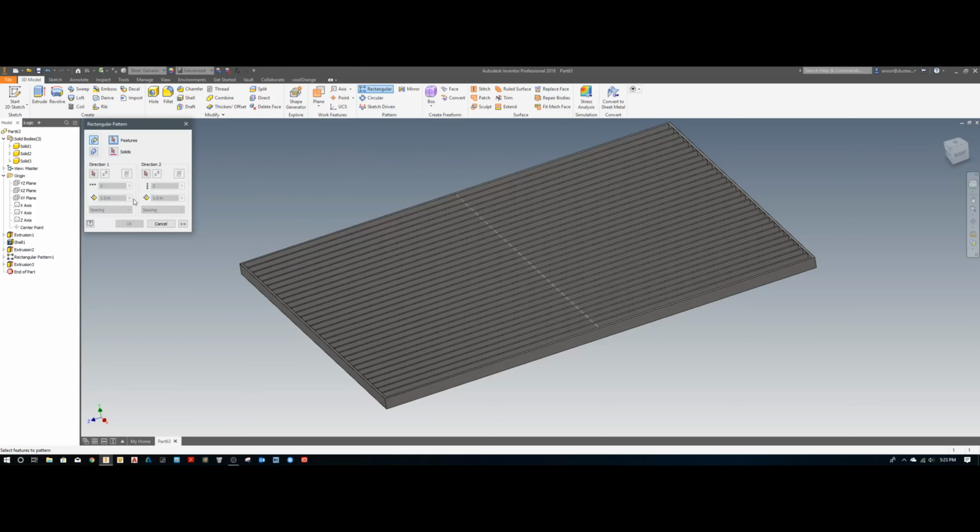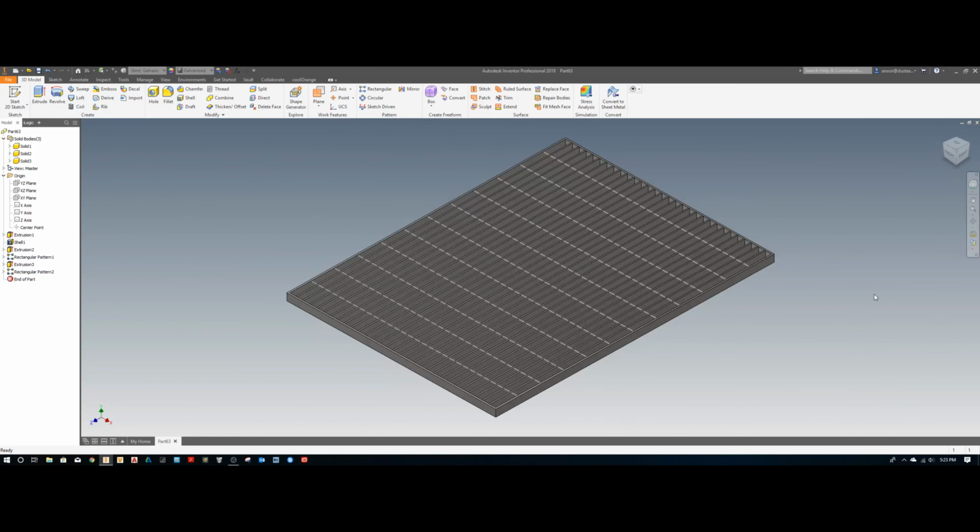So now we'll do another rectangular command and do direction. We'll do it in between. Let's try 9 first, and those are typically 4 inches. Spacing, let's try 11. All right. 13, no, 11 it is. Alrighty. So there is our grading panel.